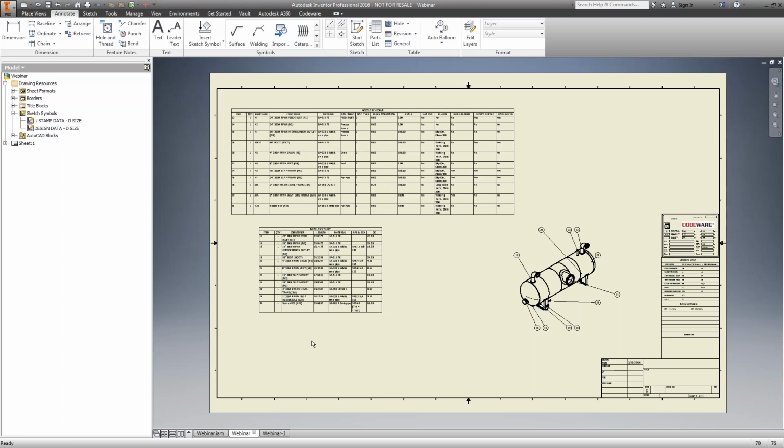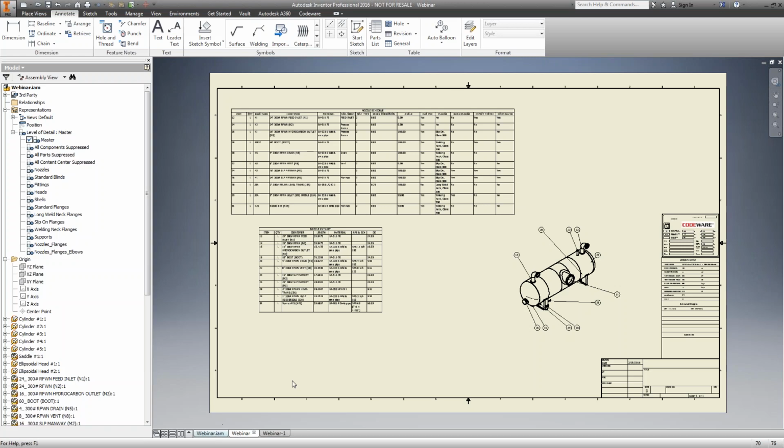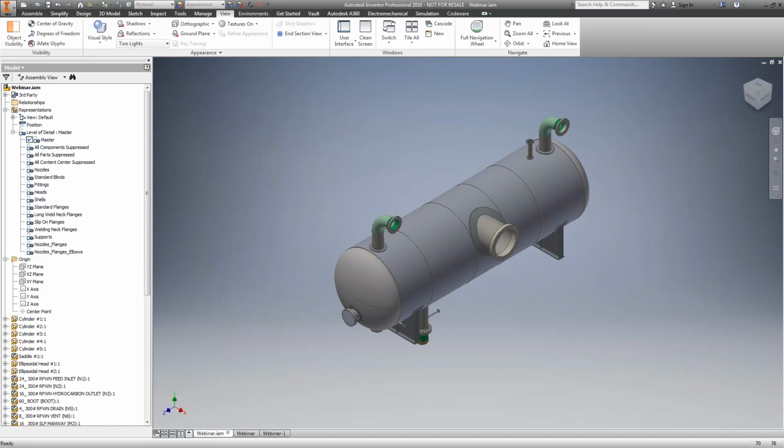So what I would encourage you to do is, when the model comes in, put in the actual internal that you're using. For example, if it's a bubble tray from Koch-Glitsch, you should be able to get solid models from their sales reps and say, I need this for my model, and actually model your actual bubble tray that way as well.